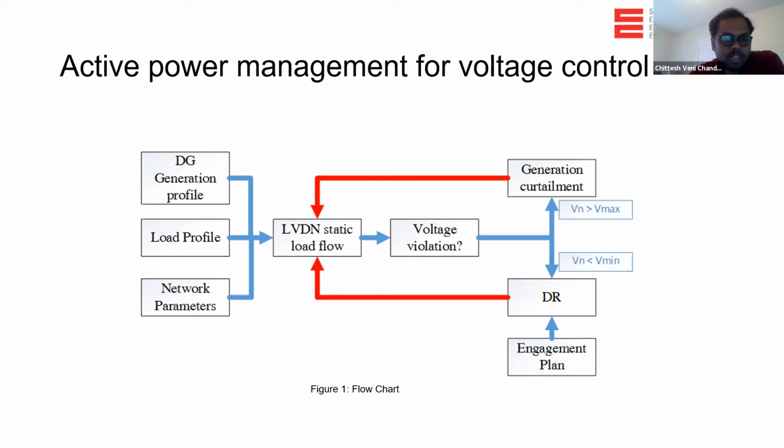We were assuming that the knowledge of the network is already available, the generation profile is already available, and the load profile is already available. We are going to use a static load flow analysis to compute the voltages, and we would be modeling the whole system in OpenDSS software, and we would be doing an unbalanced load flow.